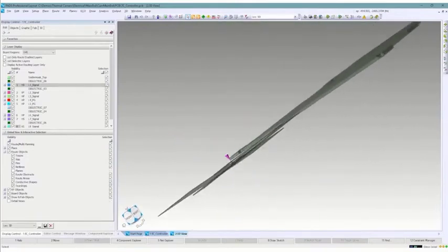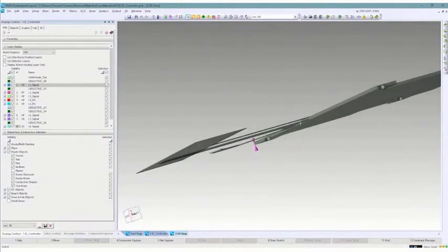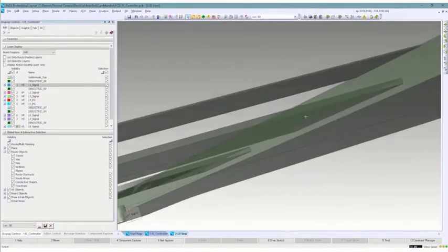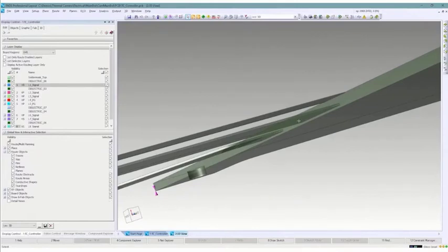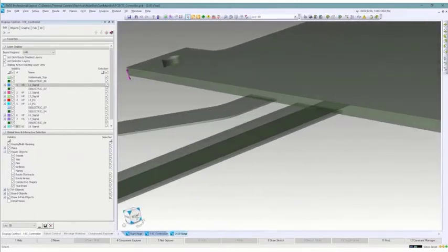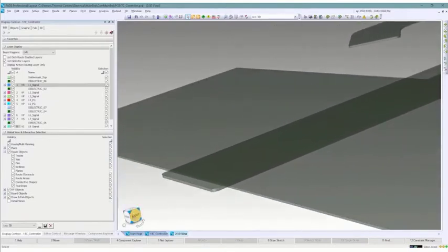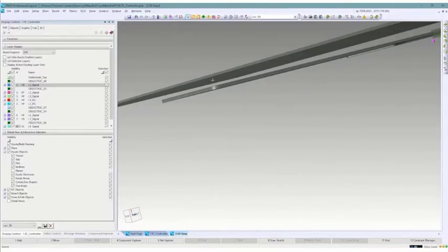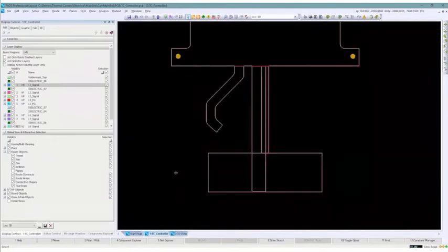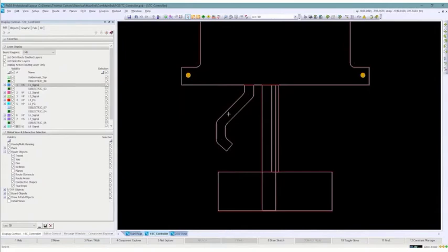So before, when they came in, they were all the same thickness, whereas now if I look at these, I can clearly see these two coming off on the internal layers, and this one, my button flex, coming off on the top. And again, where they're overlapping here, the tool now knows that these two are not connected to each other. So simplifying the entire process of dealing with your stack ups for your regions.